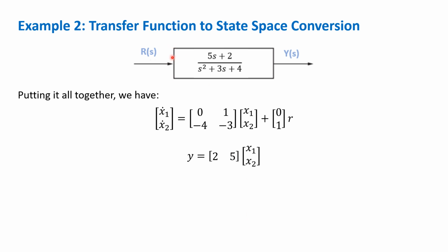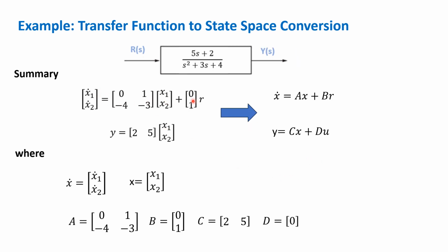So now we have the whole thing, because we solved the first set of systems in the first example, and we found the output equation. In the second example, we found what y is. So here's our solution. Again, if you want to represent this in the state space form, you can simply list what A, B, C, and D are. In our example here, here's our standard form, we would just list the matrices A, B, C, and D in that order.